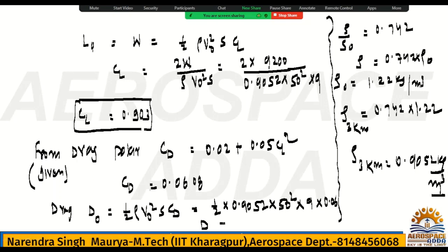So what will be the drag value? D naught. Please calculate this. 0.9052 into 50 square divided by 2. I'm getting 619. I don't know if it is correct or not. Please calculate. 619.24 Newton. Check. Yeah, this is the D naught.